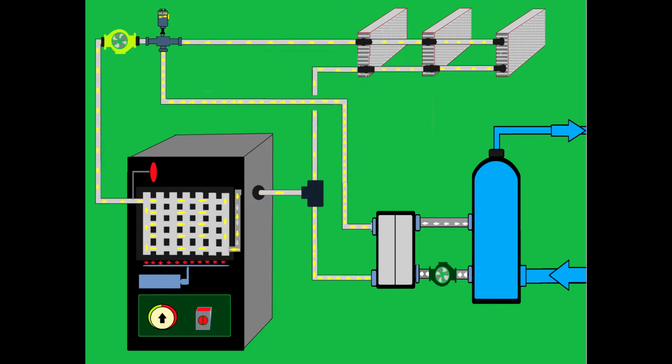When we talk about boilers, we know that before the flame is initiated, the boiler must be healthy. The pump should run, but first we have to make sure we have pressure in the system, if the system is unvented. Now the pump is running, as you will see. The two-way valve diverts the flow towards the 3 heat exchangers. Now the thermostat demands heating, and you will see the burner start the fire. You will see some little red dots pulsing.